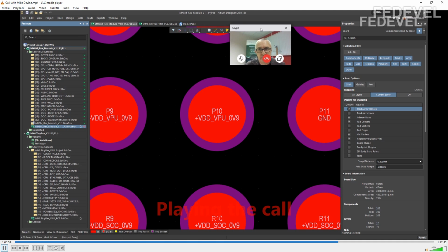So it's just tighter registration, because the dam, if you like, or the sliver web between the pads, typically really should be no less than 75 microns. Otherwise, going through the development process, you may well develop it out, which then may cause some solder bridging across from pad to pad. Okay, that's interesting. I usually use 0 or 100 micrometers. It's good to know you can go down to 75.